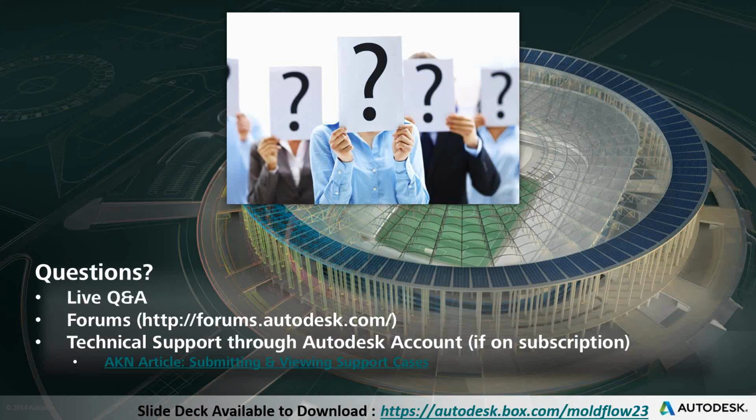That circles around to what Beth was describing a little bit earlier. It's really tough to get a yes or no answer when considering what type of mesh to use for your part, because it's not cookie cutter. We're not all using the same parts here. Whenever you're looking at a very thin part, if it's super thin, you might consider either midplane or dual domain.